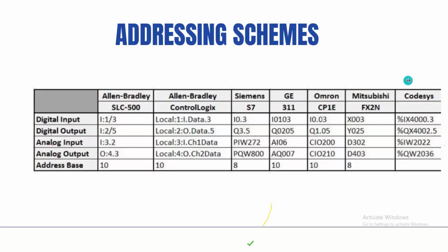CodeSys is like an open source PLC platform that people just build on. ABB uses CodeSys, Schneider uses CodeSys, and a lot of other platforms use CodeSys. The idea is to create some sort of uniform PLC standard, because the problem that people were having was that you have spent 20 years programming Allen Bradley and you want to switch over to Siemens, and then you have to start learning conventions and programming standards afresh.